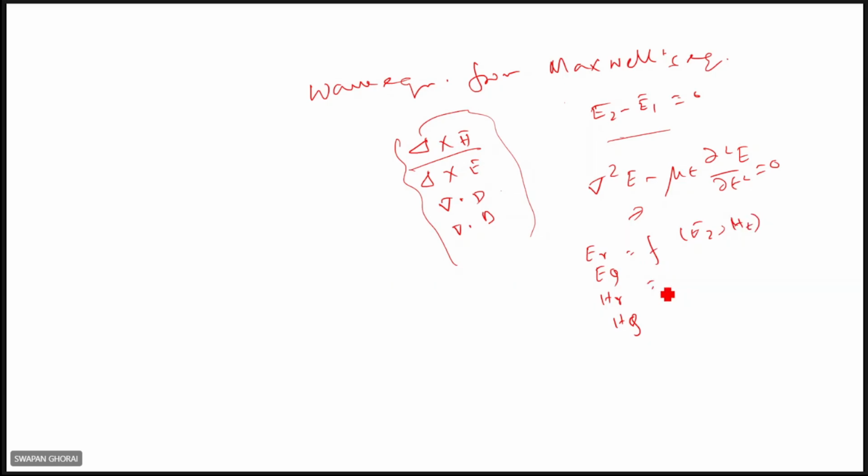Here a little bit we have modified, because the fiber is circular, so we have considered the cylindrical coordinate system r, phi, z. So we have expressed all the components in terms of the longitudinal components Ez and Hz, and from this we have considered the concept of modes.